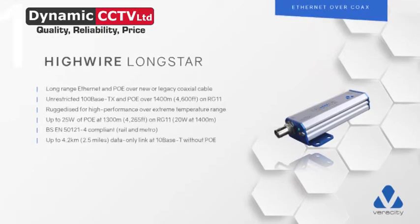As you can see, it's BS EN 50121-4 compliant, and you say, crikey, what does that mean? Well, basically, you can use this anywhere on the rail network, apart from signals. You can use this in London Underground stations, for example. But more importantly, I look at it more simplistically than that. I look at this product as if you're doing anything on the perimeter, for example, or you've got posts in car parks, and your Ultron towers, things like that, with cameras on, and you need to get at them. This product will go 1.2 kilometers with PoE and give you that connectivity.